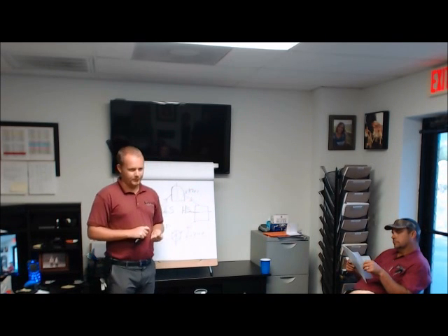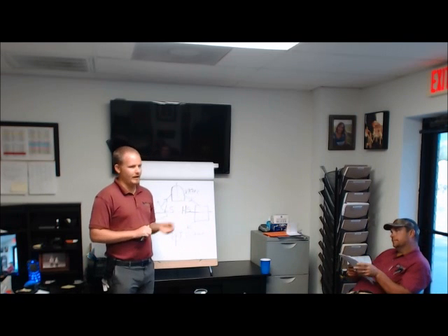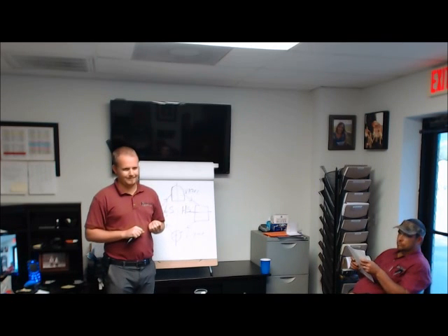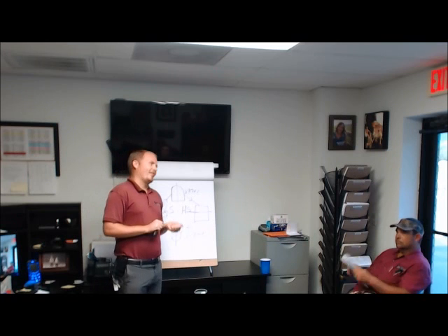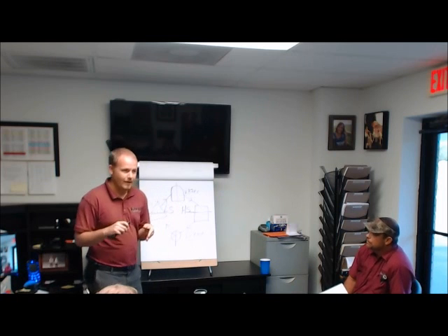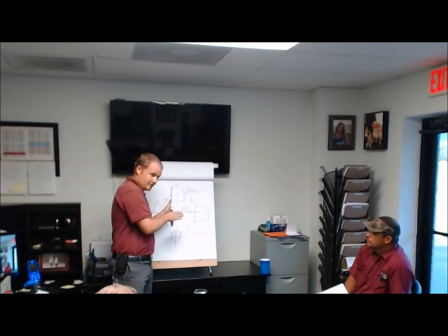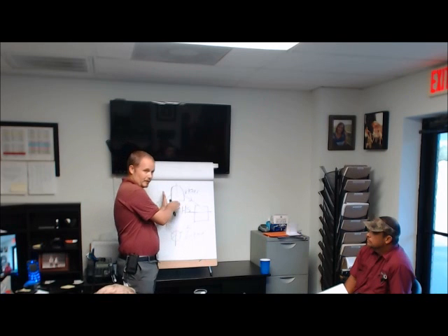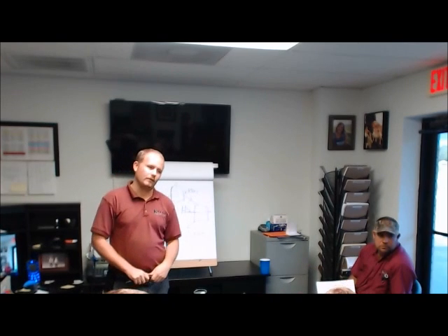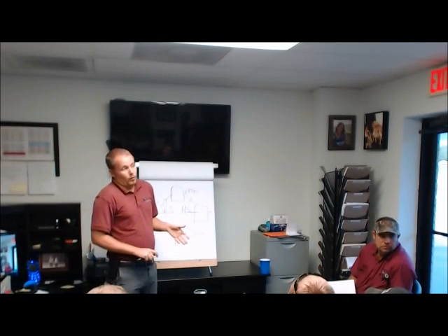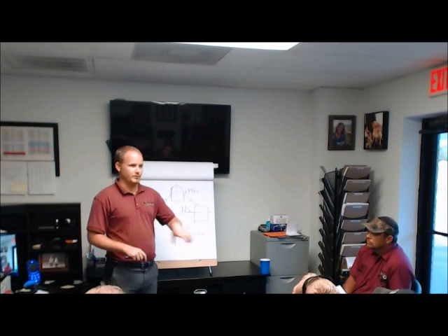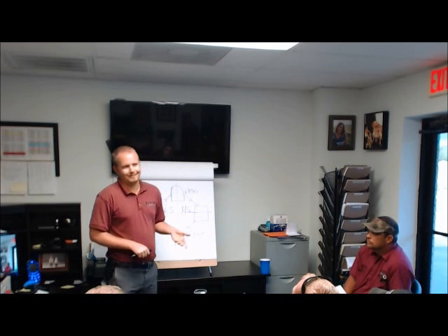Now, if you did go up to a system and you hooked up your suction gauge and it read 40 psi, what does that actually tell you? Nothing. Well, what you could say is it tells me the saturation temperature that exists within the evaporator, or rather within the suction line. But you don't know that the coil is boiling off completely from the start of the coil to the end of the coil, because what I didn't tell you is it was reading 40 psi, but it's frozen to a solid block of ice. So it doesn't tell you that.